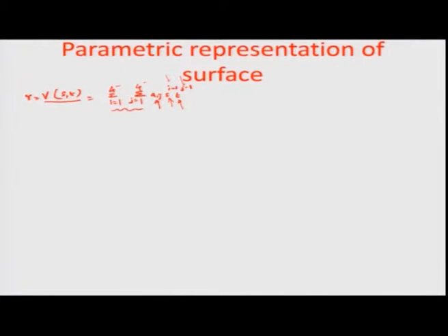Just as it was a 4 term series with t to the power 0, t to the power 1, 2 and t to the power 3, it is a cubic polynomial, you remember. In this case also, although there are 4 different indices, we want to make sure that we have two different cubic polynomials estimating both the parameters, which would eventually result in a 16 term series describing the two dimensional surface. So, we are just trying to represent V in that manner.